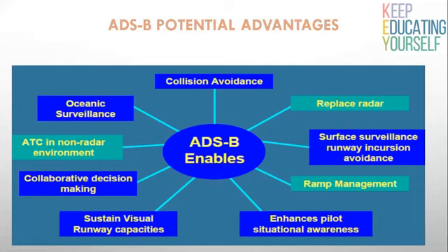Reducing unnecessary alarm rate by incorporating the ADS-B state vector, aircraft intent and other information. Use of the ACAS display as a CDTI, providing positive identification of traffic. Extending collision avoidance below 1000 feet above ground level and detecting runway incursions.